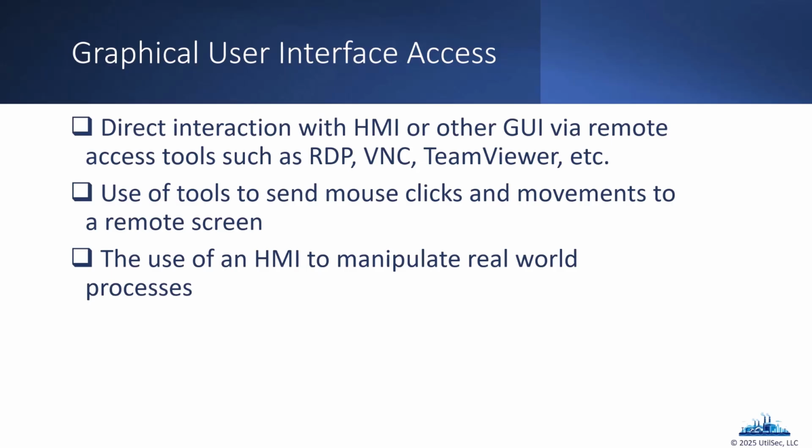So we can access the HMI. What if it's through an engineering workstation, or maybe the HMI is running Windows, so you can connect to it with remote desktop or VNC or TeamViewer, which we saw in the Oldsmar water treatment facility attack. Somebody had installed TeamViewer on the engineering workstation, made it accessible over the internet, and the attackers come in over the wire. But we can access the HMI in that case. And we can sit there and click and we can make changes to the environment.